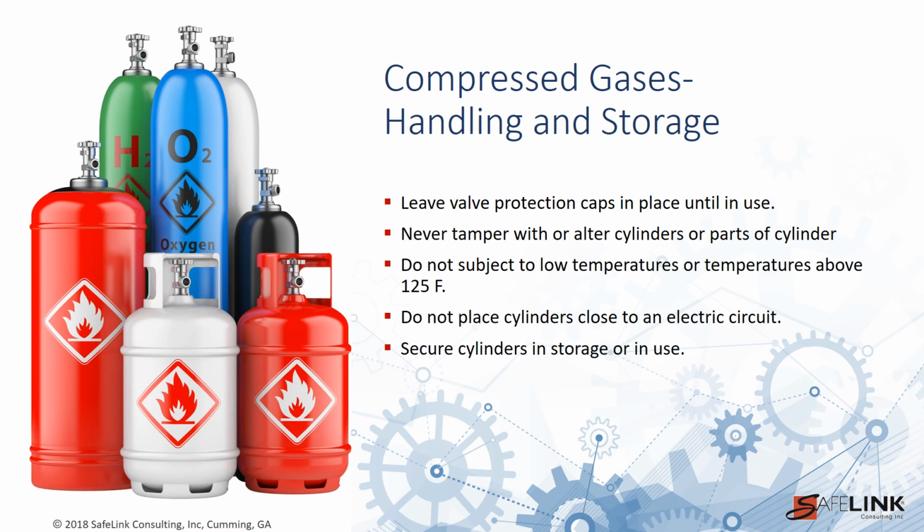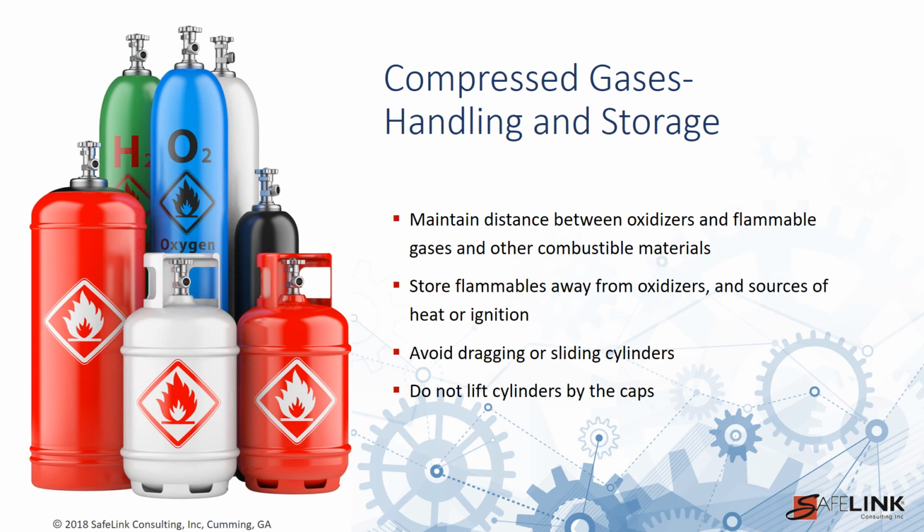Do not subject cylinders to low temperatures or temperatures above 125 degrees Fahrenheit. Do not place cylinders where they can become part of an electric circuit. Use brackets, chains, or straps around the upper third of the cylinder to secure cylinders in storage or in use.